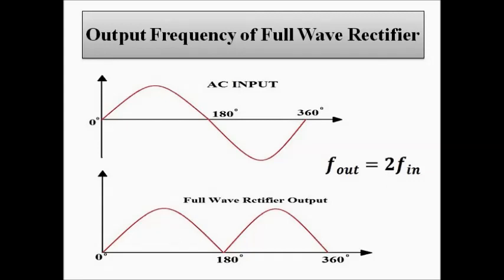Now, this is the pulsating DC output. Again, a smoothing capacitor, electrolytic type with a high discharging time constant, is used to convert it into smooth DC or almost flat DC. This is pulsating DC. So a separate video I will post about that, how this process takes place.